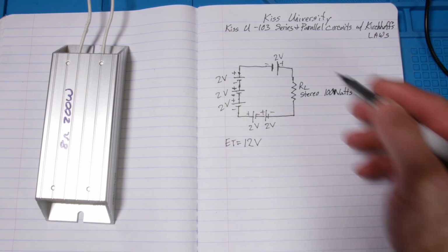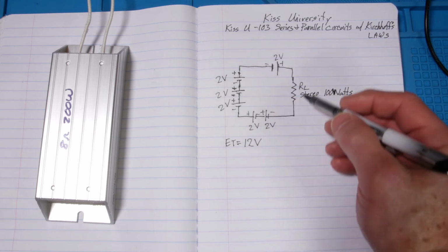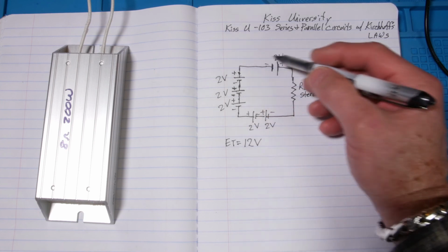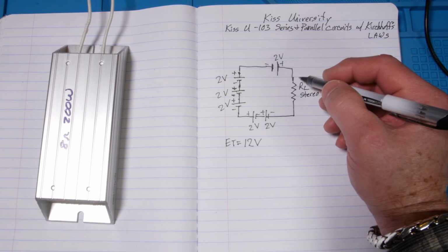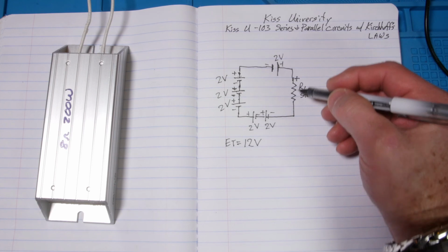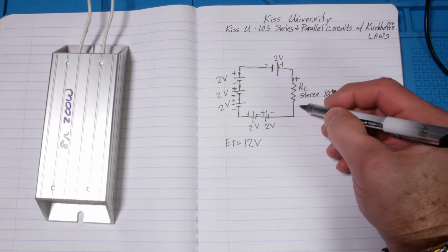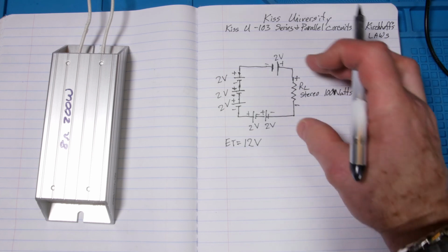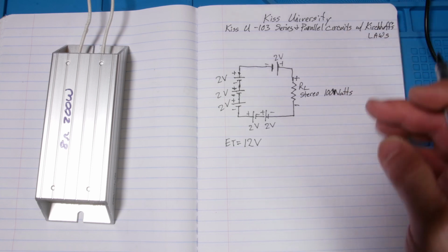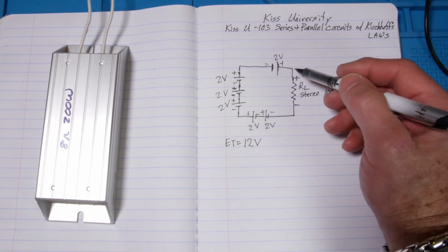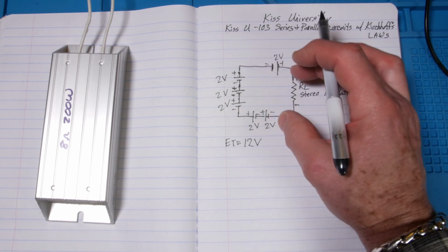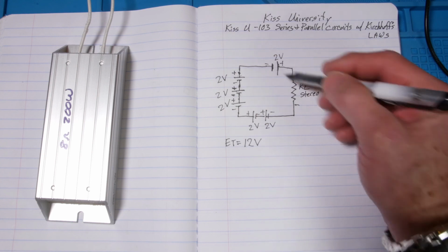It's a series circuit. Now, as we come along here, the current, it's plus here, right? So we're going to say the current flows this way, and the current comes down through, and as the current comes into the resistor, it's plus, and then as it comes out, it's minus. So if you put your voltmeter here, you'd read 12 volts, right? Because you've got all these things in series. It doesn't matter if we drew them all over here or spread out like that.